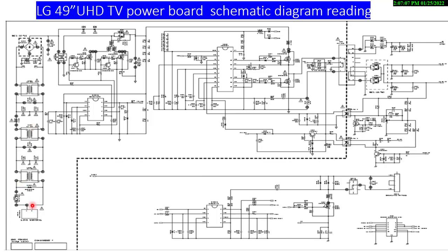So if the overcurrent protection fuse, over voltage protection, electromagnetic interference remover, inductor and capacitor are normal, this point's voltage also gets to these points. So this bridge rectifier rectifies this AC voltage to DC voltage. So at this point we will get DC voltage. This is a bypass diode to transfer the DC voltage without changing. Also here are filter capacitors.